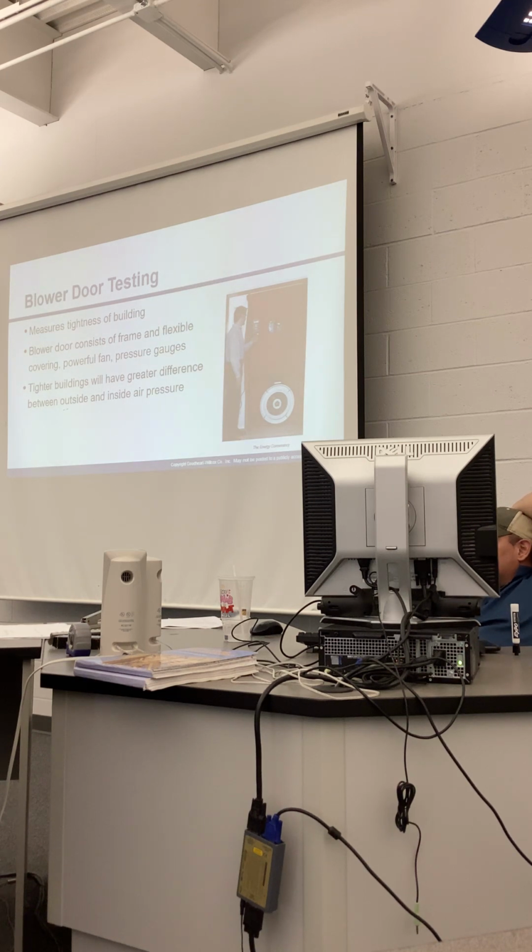Indoor air quality is higher, but there's a front-end loaded expense that goes with it. And there's a guy that sealed his house up really, really good there, blower tested everything, got it 100% sealed up. He started having problems. He goes in his laundry room and cuts a hole in the wall and puts a 12-inch vent. So his laundry room has got a vent on it that is all year long bringing in cold air or hot air, depending on what it is. But he had to have it, or otherwise the air didn't exchange in his house. So there's too much and not enough.